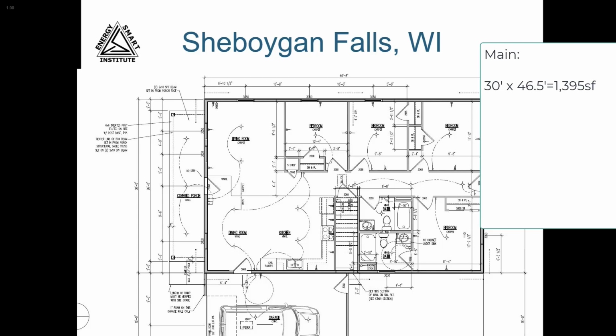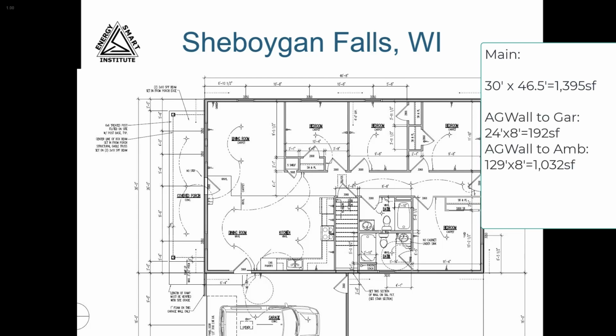This frame floor is located between conditioned levels, so we do not need to calculate any frame floor dimensions or areas. The above grade walls are all constructed alike, 2 by 6 with R19 batt insulation, and their locations, lengths, and heights match the locations, lengths, and heights of the foundation walls. So we can just copy those wall areas to this level as well. The conditioned volume will also match since we have the same area and the same ceiling height.